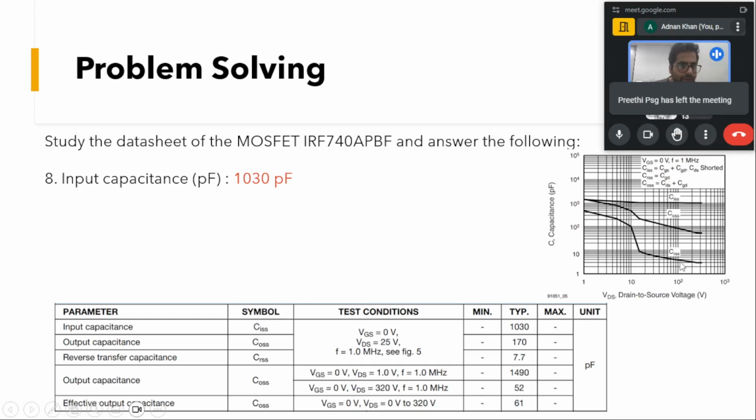So you can see for different VDS voltages, if you open up the graph of any of the devices, it shall follow whatever is given in the data sheets, provided the test conditions at which the graph is taken are the same. This is the graph to check the capacitance, the variation of the capacitance. You can see the data provided by the manufacturer, because manufacturers test these devices and provide the data, and you can go through the graph sections of the data sheet.